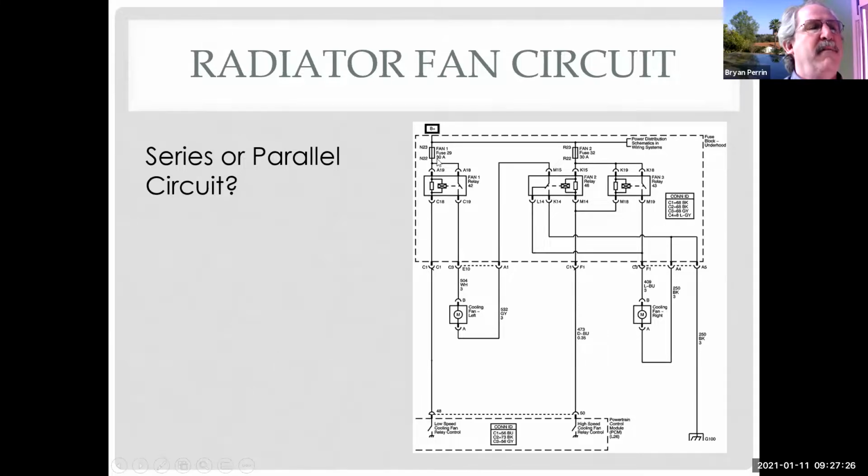And then I have power here, and the power comes out to here, comes out over to here for the on off, and it comes into here for the on off. So if we turn this relay on, the left fan comes on and it has to get to ground. So if the relay is in this position, it's going to come over to here and it would have to, what? Go through here to get to ground. Isn't that a long series circuit?